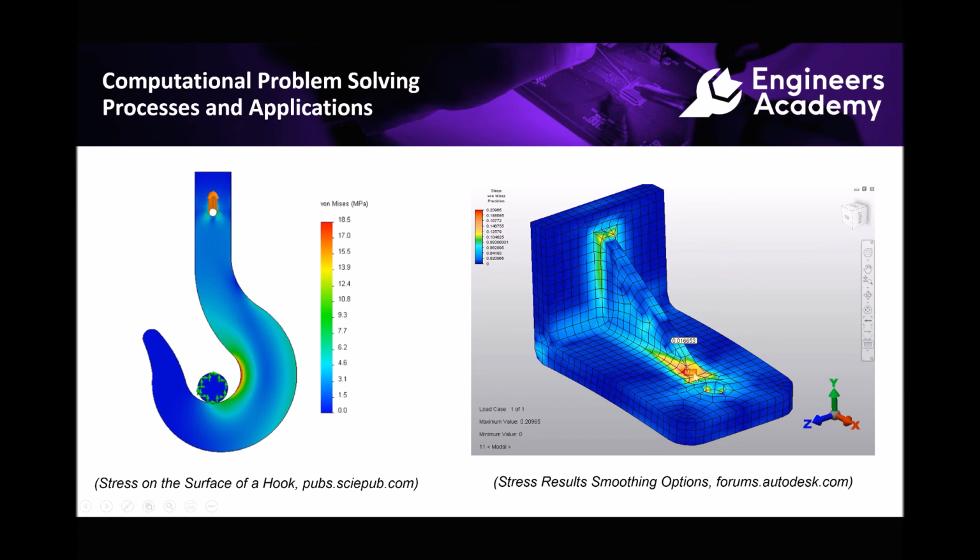So essentially what the software does is it produces a simultaneous equation for every single one of these nodes. So we have a node here next to the hole. The software package is going to look at what it knows about the forces applied at the hole, and it's going to generate a simultaneous equation based on that information and information for all of the surrounding nodes. Again, at the back of the bracket, we will know something about the fixings on the back of this plate. So at each of these nodal points, the software is going to look at the back of that plate and take what's known or defined and create a simultaneous equation for all surrounding points. So, as an example, we might end up with hundreds or thousands of simultaneous equations, which are difficult to solve.